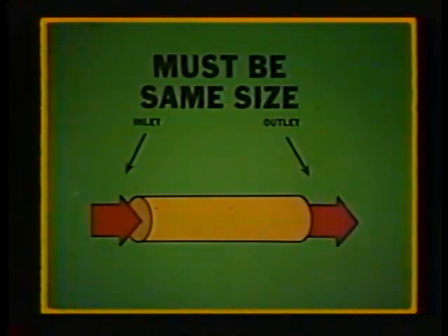The inlet and outlet lines of all instruments must be of the same size, unless you are increasing or decreasing volume from another instrument. And any hose that has become hard, has developed cracks, or starts separating should be replaced.